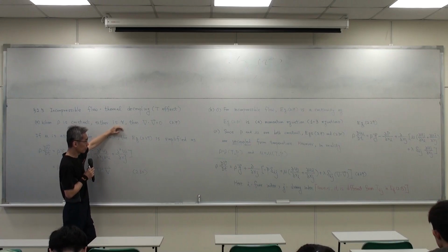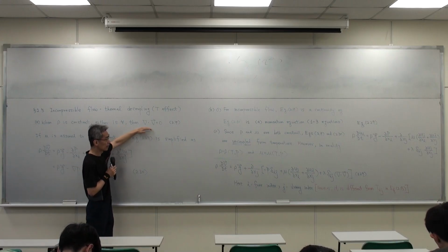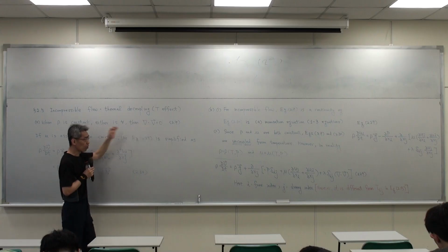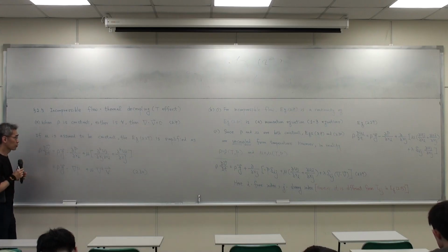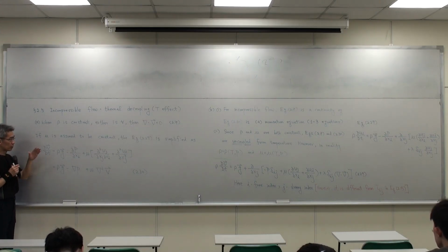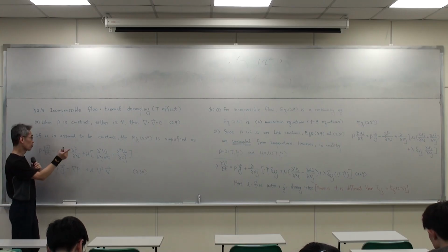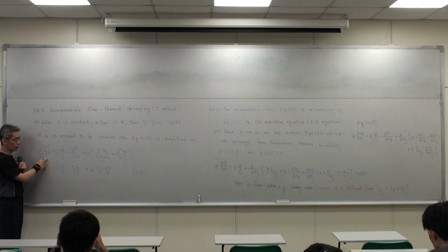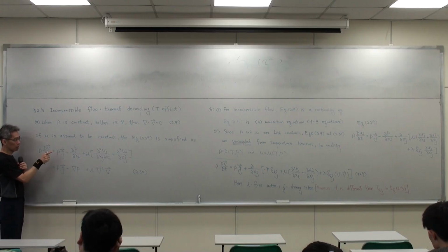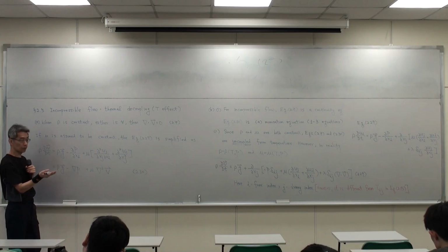So we will have a continuity equation like this. This is what we talked about before in the mass conservation equation. And in incompressible flow, if we substitute that force into this equation, the final term with the second viscosity will disappear because of the continuity equation.